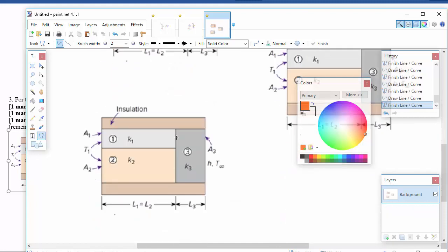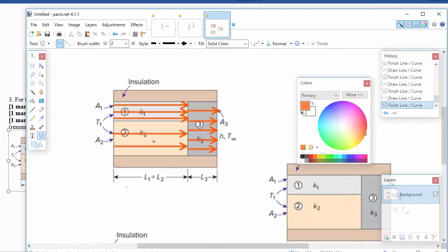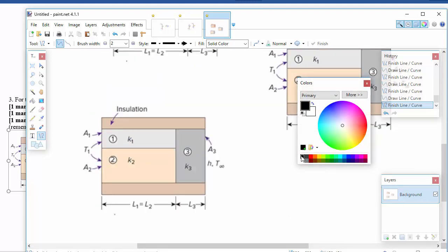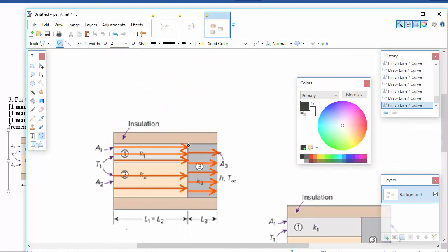That's the isothermal normal assumption. Under the adiabatic parallel assumption, instead, rather than imagining this first situation, where you'd say we've got these two things in parallel, and that equivalent thing is in series with this whole equivalent thing, which is the effect of using that assumption to add the resistances, you could say, all right, let's say that this is kind of like a split right there, and view K3 as two different parts. So in this first one, you kind of make a big deal about that line and view this as in parallel, and then add that in series with this.